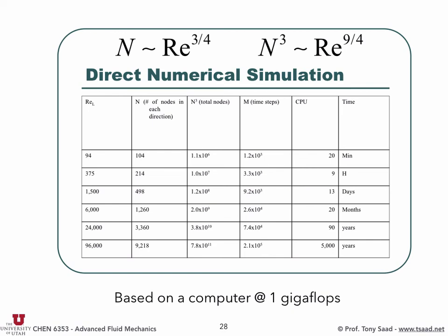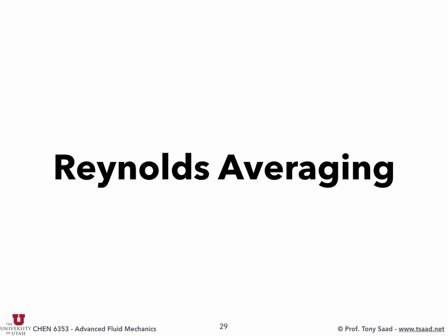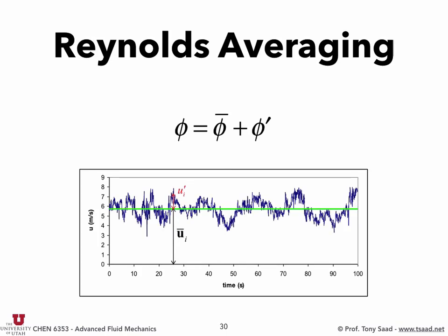Okay, all right. So we're not going to talk about LES. We're going to just jump directly into Reynolds averaging, and we don't have to call it Reynolds averaging. We just call it averaging. And the idea here is rather than taking the instantaneous velocity profile, what we are generally interested in as engineers, even scientists, is an average sense of what the flow looks like. Okay, just an average property of what the flow looks like. So Reynolds said, okay, let's decompose the total velocity field or any property in the flow, because it's not only the velocity that's fluctuating, it's also the pressure.